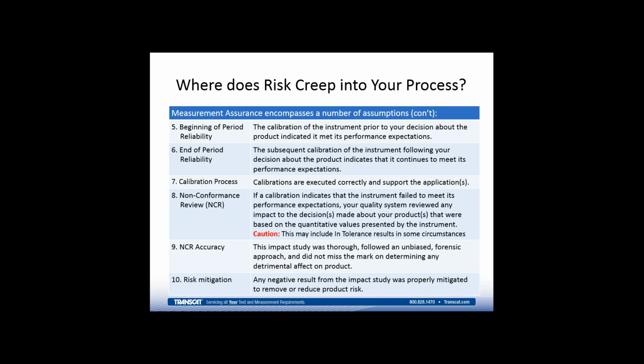That's usually how people think of it. Take a look at the calibration at the end of the period of its cal interval and see if there were any impact at all, if it was out of tolerance, on the product. But this concept takes it a step further and says, wait a minute, there could be an in-tolerance situation that causes product false accept. And that's what we're going to show in some of the examples.